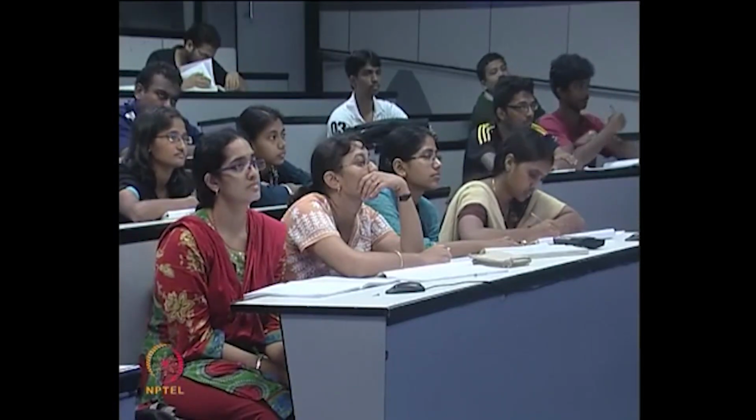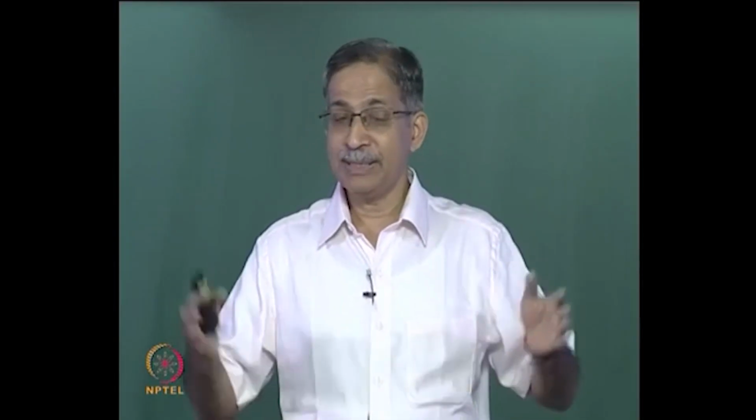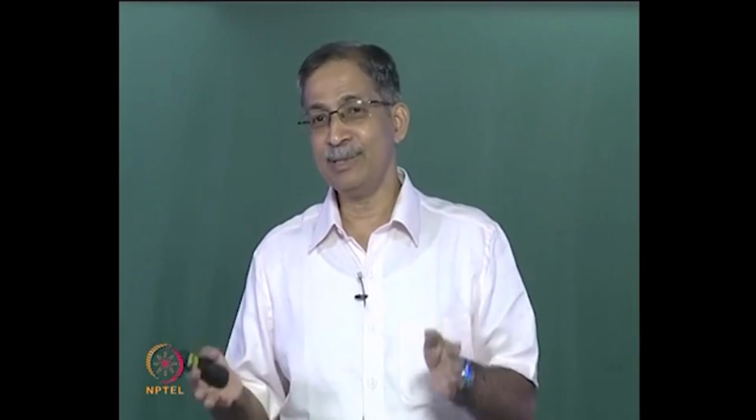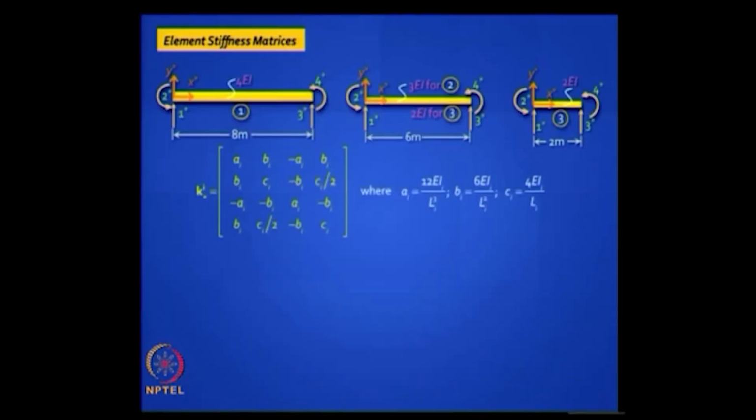Because we are doing superposition, we are taking a primary structure, putting the distributed loads, and we are adding this loading to that structure. So in the primary structure there are no displacements, d1, d2, d3, d4, d5 are 0, so that is why this must be giving you the final displacement. Is it clear? But you are right, we also have to add the indirect loads, which we will in the formulation. Okay, so next step is to generate the stiffness matrices.